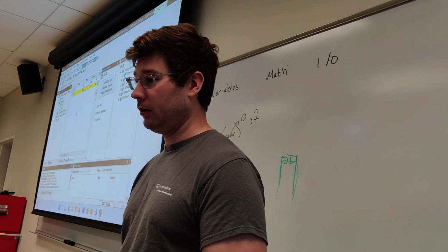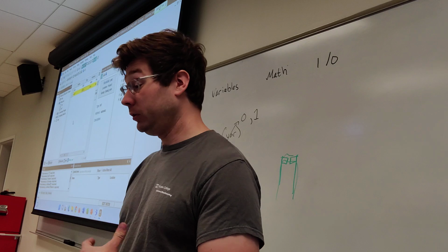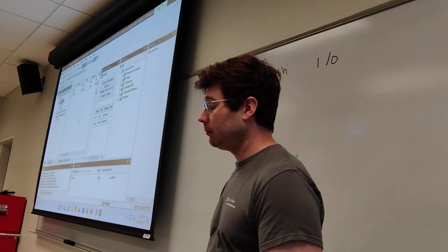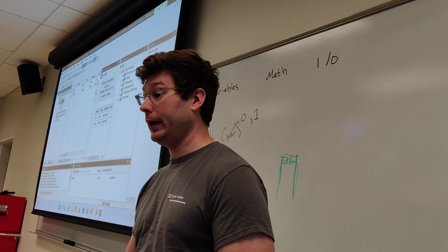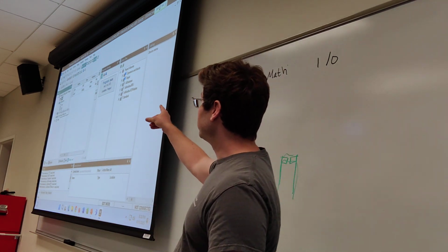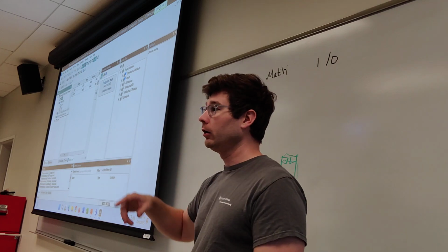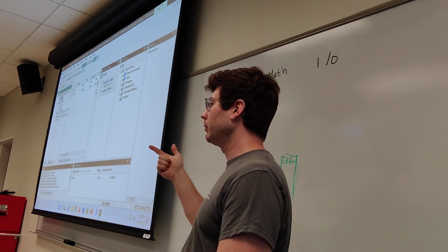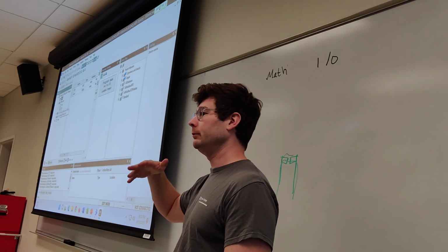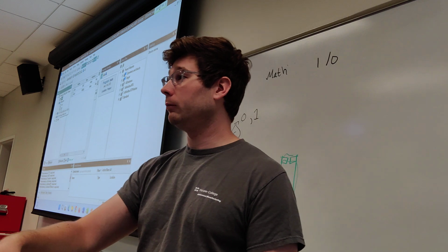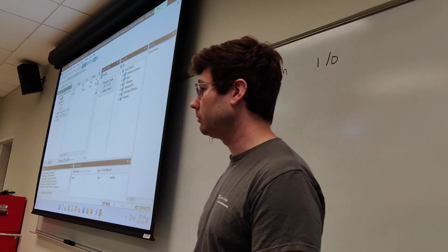This is where we can put really anything we want. Global means that any program we make, so if we make a program other than main, if we had some other programs doing things as well, they could also see what's in here. So if we had a master state variable, like run or stop, and we wanted all of our programs to see that variable and respond accordingly, we would want to put that variable in the global variables, because then every program could see it.